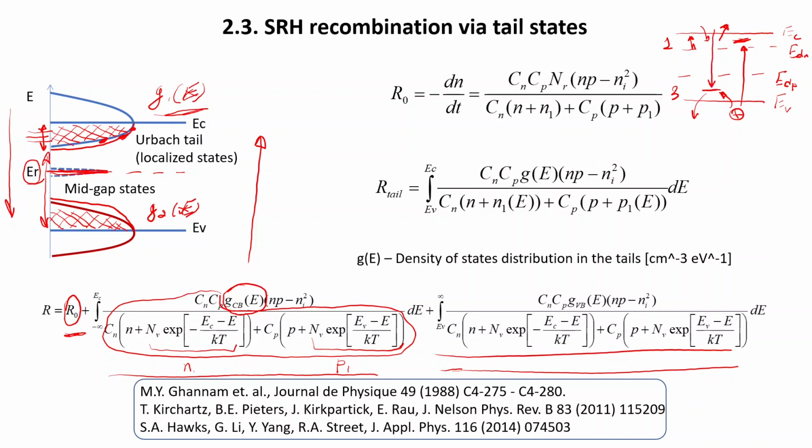So it will be the same story. They will not participate in the reduction of charge carrier concentration, but they will reduce the mobility of holes. And that, of course, is not good, but in terms of recombination, it will not be an efficient recombination center.